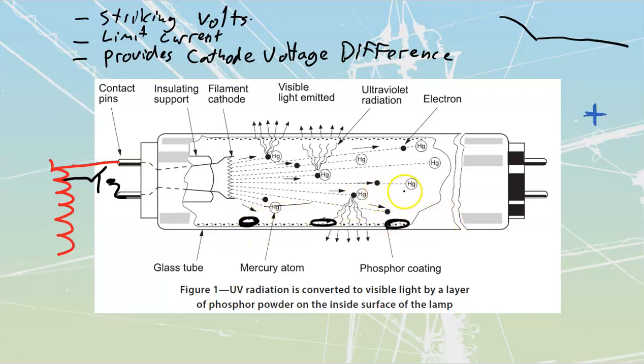So what you can do is take your tube out and flip it 180 degrees. Whatever was the bottom part of the tube, you move up to the top again, and then all of that mercury, which has accumulated on the bottom, is obviously going to have to start moving through the lamp again. You get more light out of it. If you're coming in there for a customer, just replace the lamps if it's already getting to that blackening. But if it's in your own house and your light's getting just a little bit dull and you don't have time to run down to the Home Depot to pick up a set of tubes, flip the tubes and it actually does make a difference.